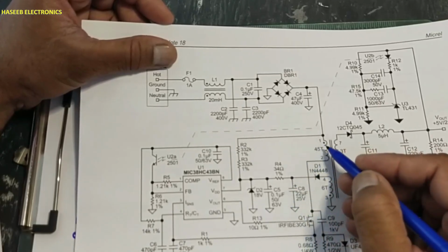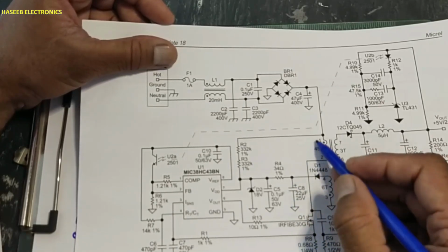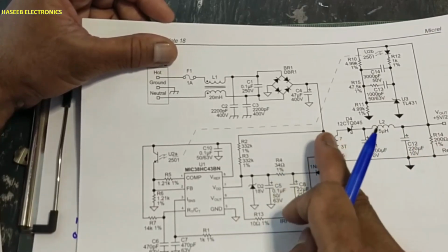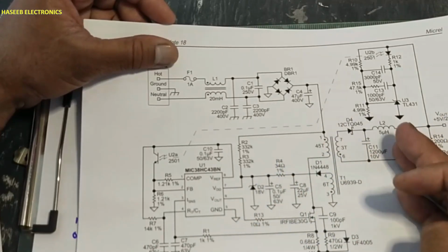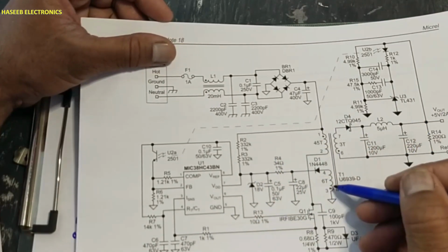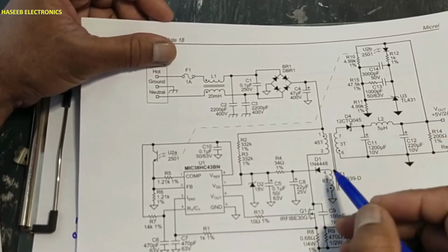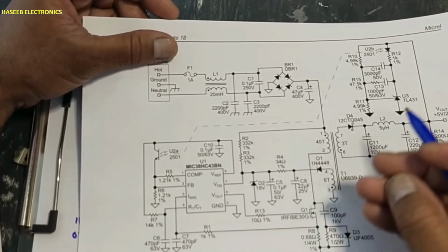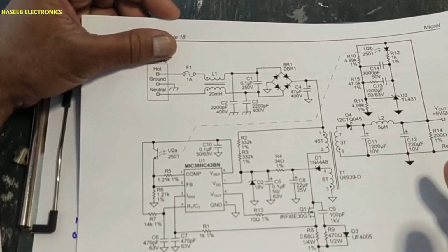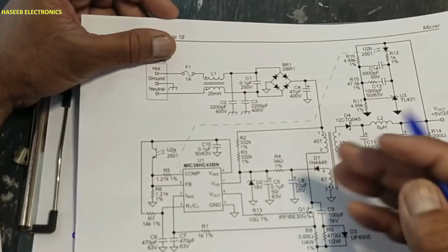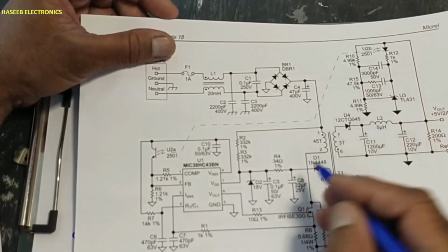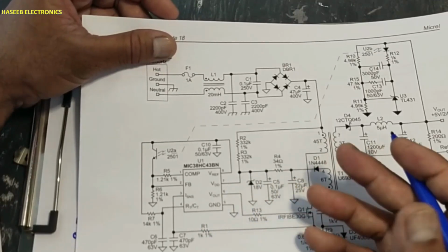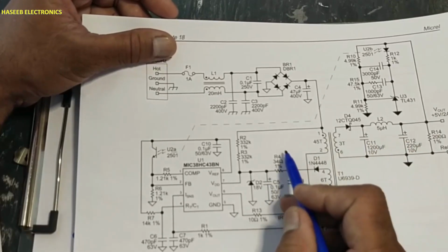In turn-on time, it will store magnetic energy in the core, in the primary winding. When this MOSFET turns off, this stored energy is transferred to the output side and to this winding. If it provides slightly high voltage, a VCC current limit resistor is used here. If you receive slightly more voltage, say we calculated the circuit to provide 16 volt but it is providing 40 volt, the voltage can be dropped by calculating the maximum required current, that is 17 milliampere. A resistor value will be connected here.